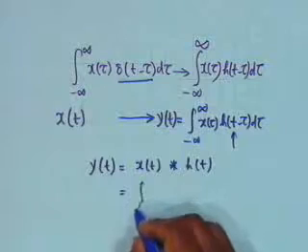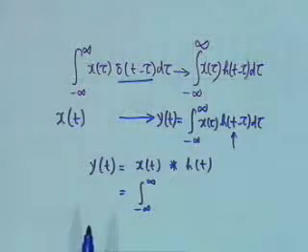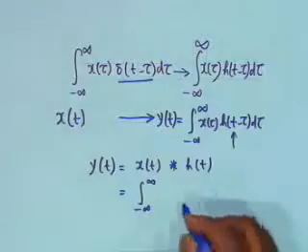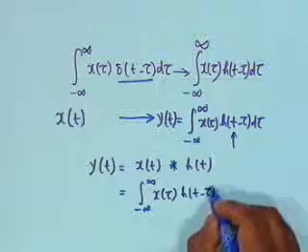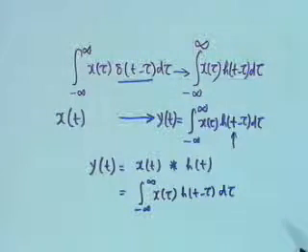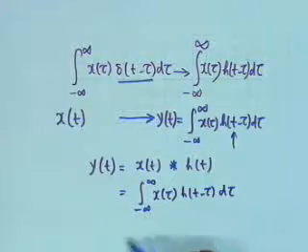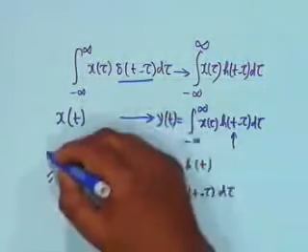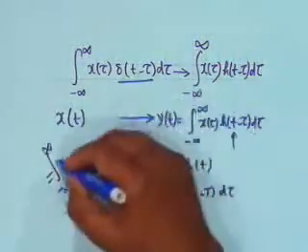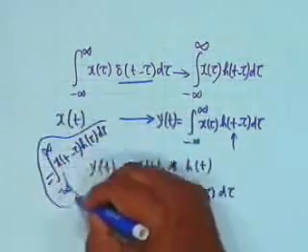And in the continuous time domain, the convolution is defined in terms of an integration, whereas in the discrete time domain it is a double infinite summation. In the continuous time case it is x of tau h t minus tau d tau, and if you make a change of variable, it's very easy to show that you can either delay h or you can delay x. In other words, it is the same as minus infinity to plus infinity, x of t minus tau, h of tau, d tau. It doesn't make a difference,